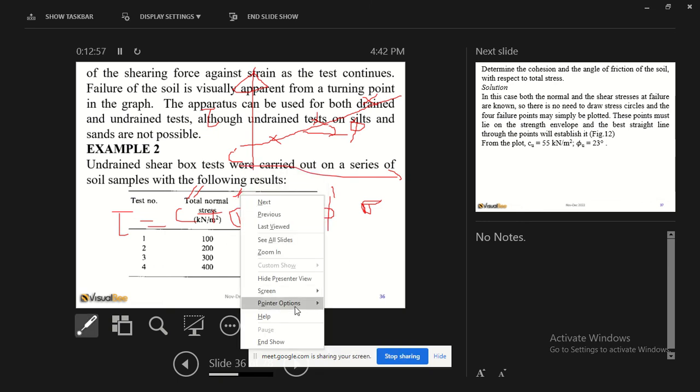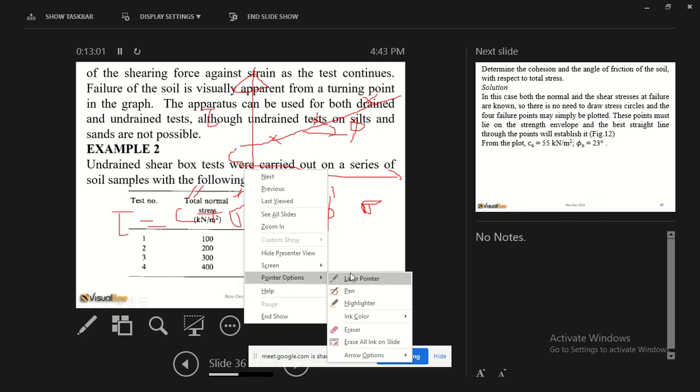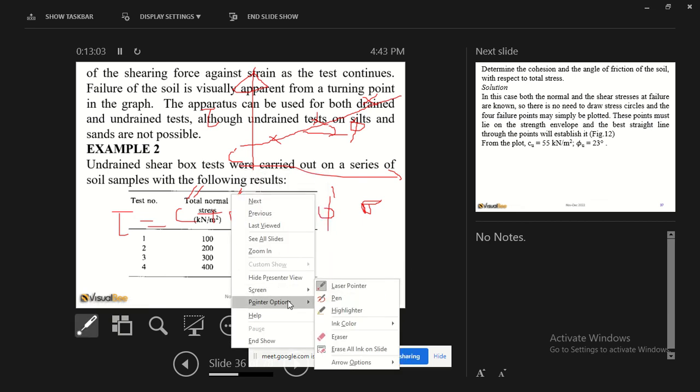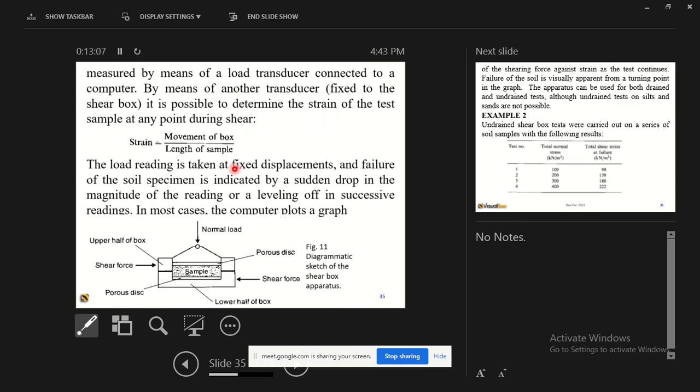Now for the shear box test, we cannot have effective stress parameters because all we can measure are total stress parameters. Please note, these are porous discs here. This test is usually done underwater, because you want the weakest condition, and the weakest condition is when it is underwater.